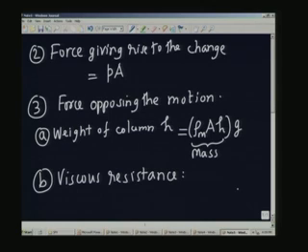I am assuming that when it is moving up, it immediately goes into the fully developed flow, which is an assumption. So, it is moving up with a parabolic velocity profile, but I am looking at two things: the mean velocity, dH by dt, I will call the mean velocity. There is a velocity profile in the tube due to this viscous effect, because at the central line of the tube the velocity will be higher, and the velocity at the sides where it is in contact with the surface of the tube is 0. Let us look at it as a simple modeling thing, because everything ultimately comes into how we look at it. I am not saying that this is exactly what is going to happen. What is happening is how I am describing it. Okay. So, with this background, let us look at the viscous resistance, that will be given by